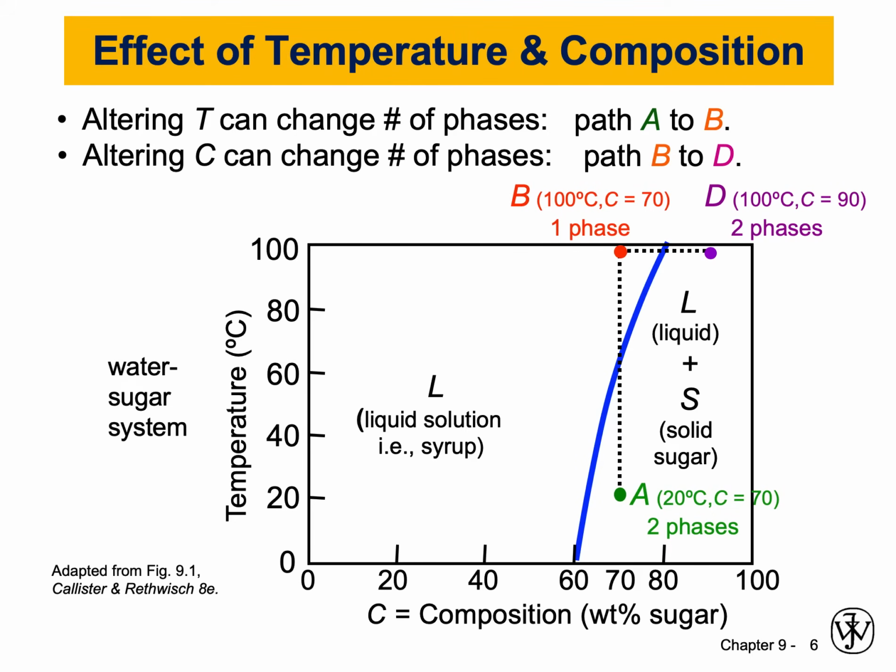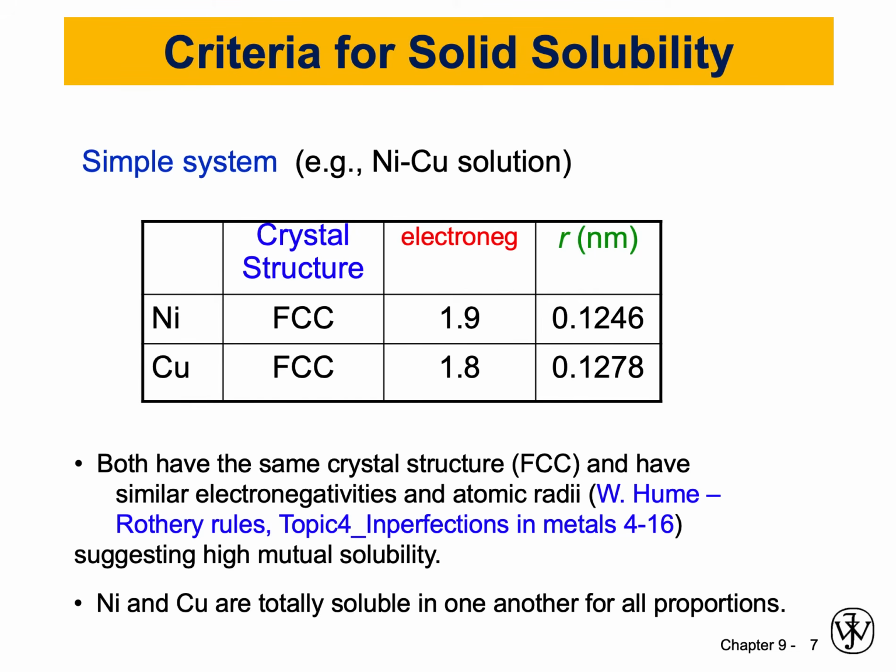Before I finish this video, I want to highlight one more point: there is a criteria for solid solubility, and the criteria is that you need to have two elements and they need to be as similar to each other as possible. And if you remember from our previous